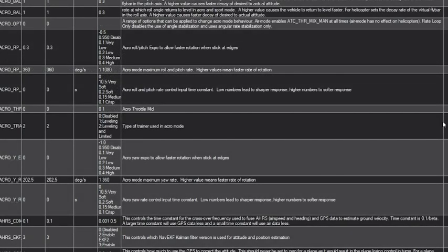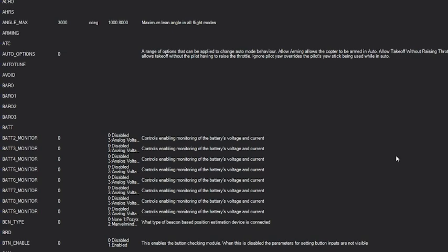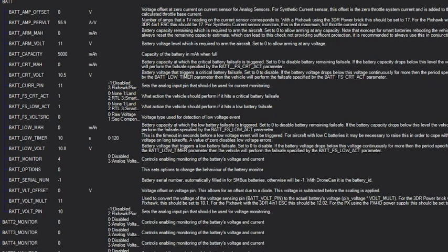Here, go to the full parameter list, or you can even go to the full parameter tree on this one. Remember, under this configuration tab still. Give it a second to load. And we're just going to review a lot of these battery ones that we've altered. So go ahead and search BATT on the right-hand side. Come over to this third value.